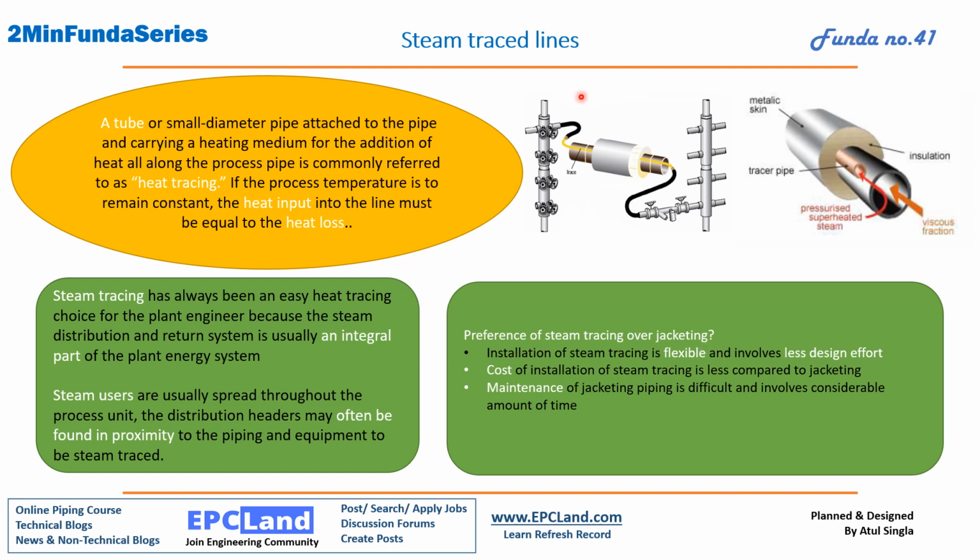Now there is one steam manifold, then a condensate manifold. This is a very common thing: we get the supply, and then we collect the condensation in the condensation manifolds. Okay, so this is a very useful concept to maintain the temperature inside. At the same time, installation of steam tracing is very flexible because we are getting steam very easily. Distribution headers are always nearby, so we can always take tappings and do this kind of arrangement. Cost of installation is very low as compared to jacketing. Maintenance of jacketed pipe is very difficult as compared to steam manifolds and everything. So it is a very useful concept to maintain the temperature inside the pipe.